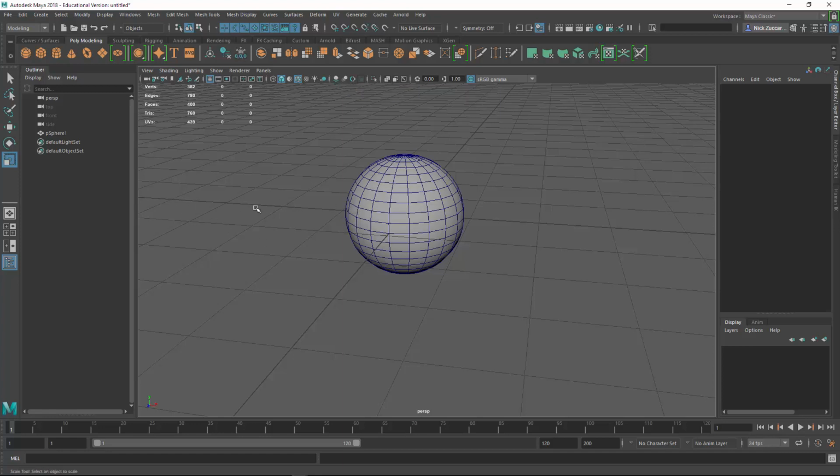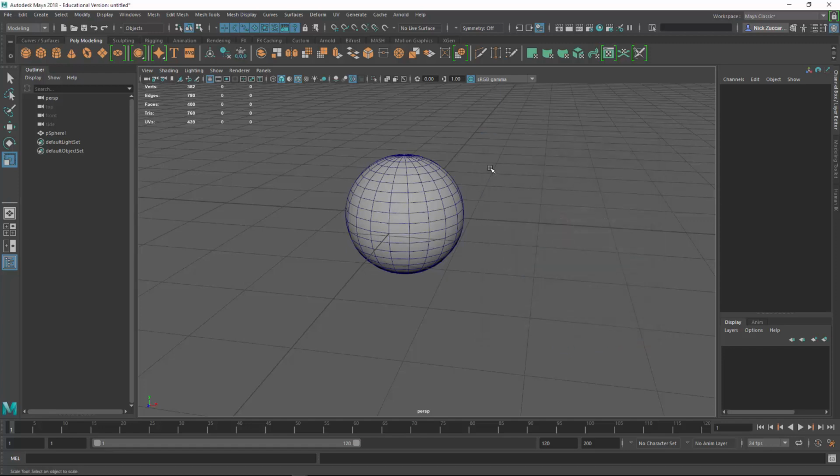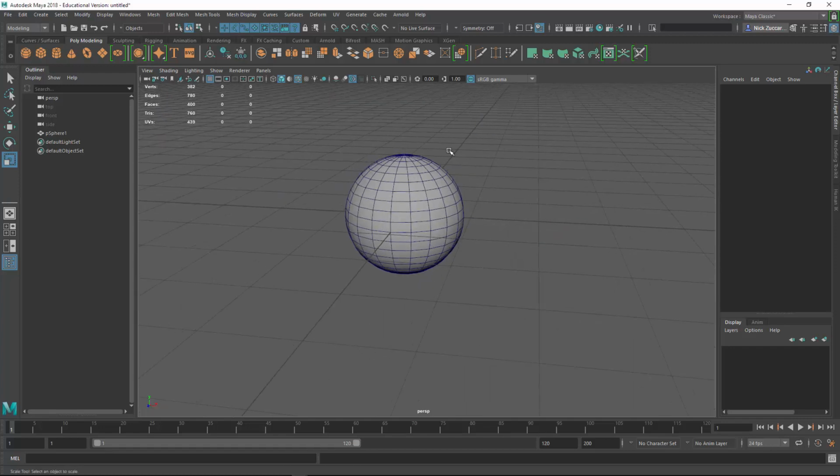and I really like this one where you can see, right now, these lines are not anti-aliased so well, so it looks jaggedy. If you turn this on, this will turn on anti-aliasing and it'll give you a better quality for what you're looking at for the wireframes. Now one thing I will show you is going into renderer, go to Viewport 2.0, go to the option box for this. If you want to turn on anti-aliasing and turn that up a little bit more, you can maybe turn on smooth wireframe, and then you can turn on the sample count. Obviously the higher the count, it's going to be a little bit more expensive, but the quality might look a little bit better, right? And so you can put it on the highest quality level there for that.